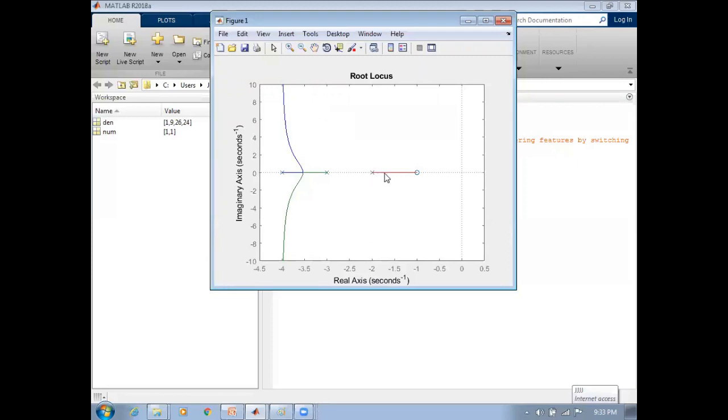When k increases, there is a movement of these poles, and when k reaches infinity, it reaches the 0 here. Whereas on the other side, we have two adjacently placed poles. Therefore, there exists a minimum of one breakaway point as it is in the region of root locus. This pole exactly breaks away, and it reaches infinity when k reaches infinity.